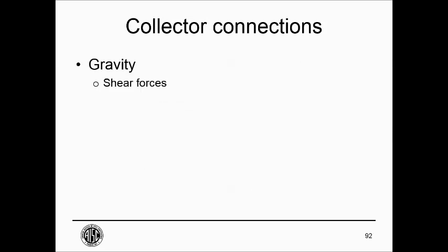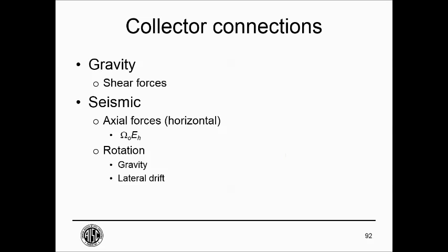We have collector connections that we have to worry about. There are shear forces as well as horizontal forces due to seismic. Shear forces because it's a gravity beam, and horizontal forces because it's a collector. Those are amplified forces, omega sub O times E sub H.